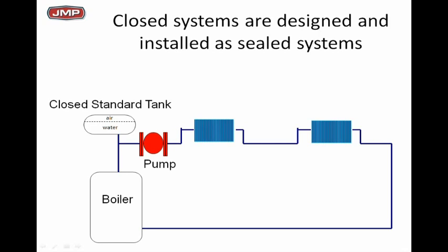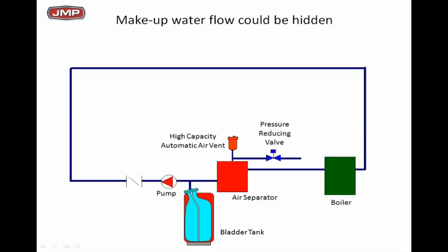Your plumbing systems would be open systems because the water goes through one time, we use it, and we go to drain with it. So that's an open system. Cooling towers, condenser water, would normally be an open system with an open type of a cooling tower. So we're going to be focused today on closed systems, air control, and system pressurization on modern chilled water, modern hot water heating systems. That's where we're going to focus our time.